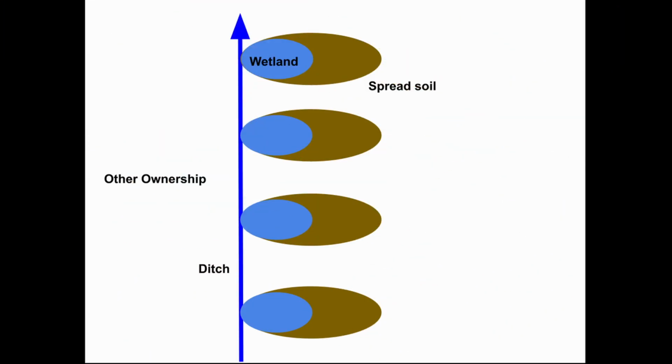We designed a series of wetlands to build along the ditch. The wetlands would be built to capture soil before it entered Quamachin Lake. We could only build the wetlands on the right side of the ditch because a different individual owned land on the other side of the ditch. I placed the wetlands along the ditch every 2-foot change in elevation. Dams were not built across the ditch because this would have flooded the neighboring property. The soil to be removed from digging the wetland basins would be spread along the outside and downhill edge of each wetland. The spillway for each wetland was the section of ditch that was left in between each wetland. The elevation of the bottom of the ditch would become the elevation of the spillway for each wetland being built.